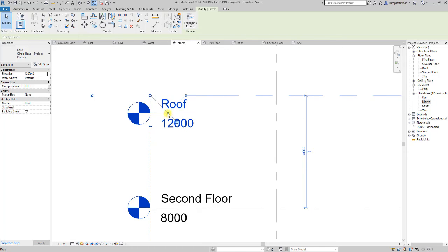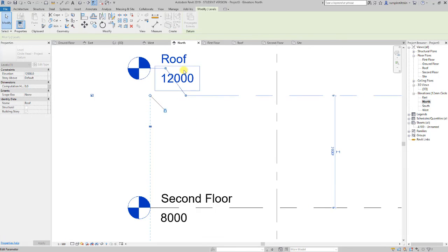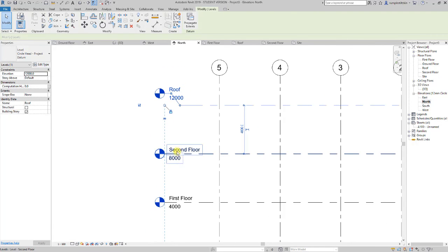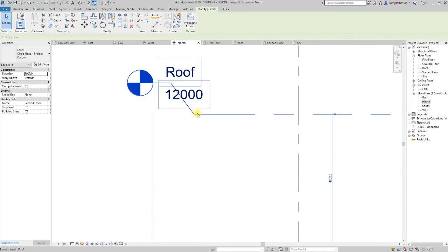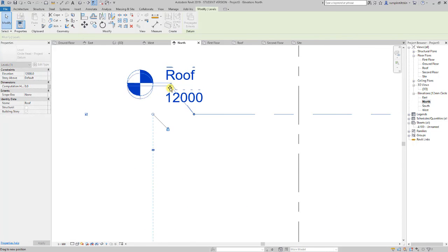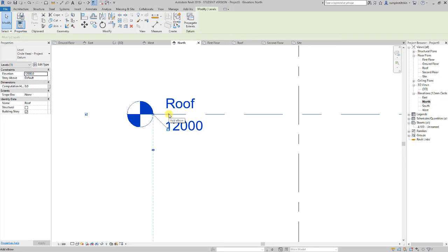Another thing, you've got this thing here, which is the elbow. So I can add an elbow. Sometimes when you're using different scales, the elbow means that you can move these away from each other, which is a really useful thing. To get rid of the elbow, just select the line and then bring that grip back down to straighten it up. That gets rid of the elbow and just leaves you with the symbol to add an elbow. And then you've got this thing here that either hides it or reveals it.